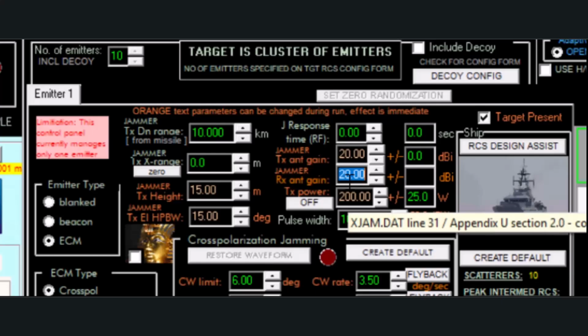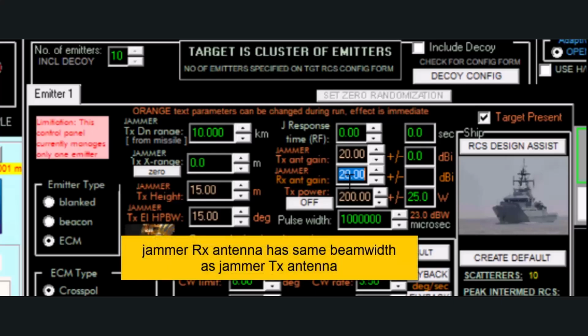That's important because we are interested in jam detection, right? So how much power are we getting from that seeker? Seeker's configured. It's got a transmit antenna gain. It's got a transmitter power. It's a certain distance away. Here's the propagation. But what's on the receive side? Because we want to make sure we can detect the signal. So that's why the receive antenna is important.